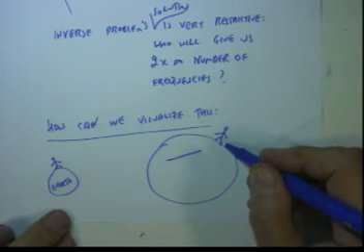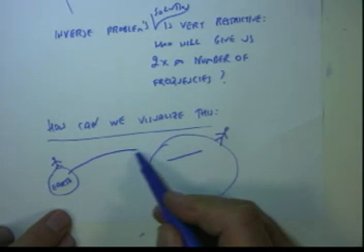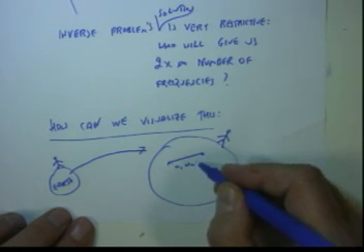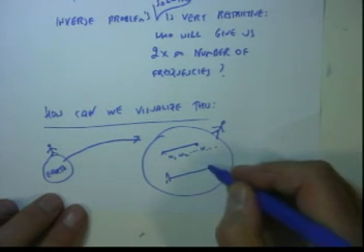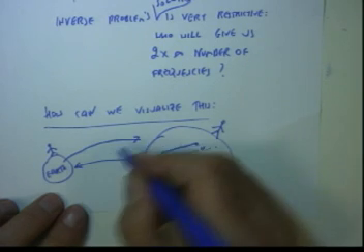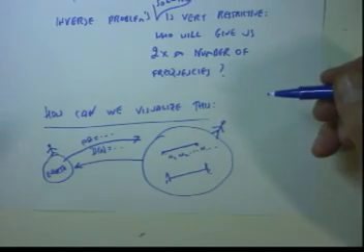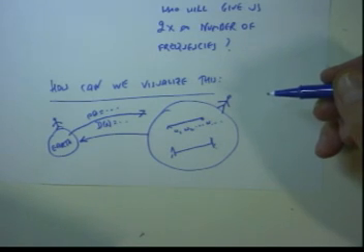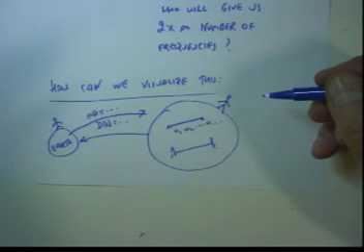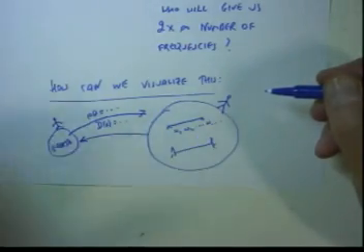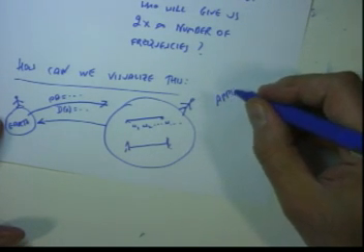Now, this person, we are helping. We know how to solve the problem. So he has to measure frequencies simply supported, omega 1, omega 2, etc., many omegas. Then for clamped. Then he has to pass this information. Then we will tell him what rho A equals and what D(x) is. So it is a very artificial imagining of the situation. Because if I know infinite amount of frequencies, probably I could also just measure D(x). To find so many natural frequencies is much more difficult than to just look at the beam and measure what is happening. So it appears to be very artificial.